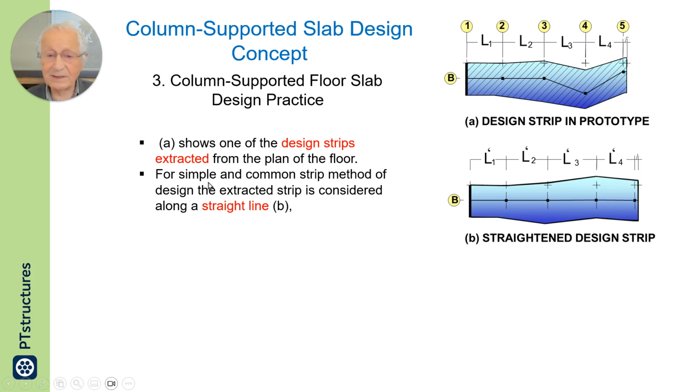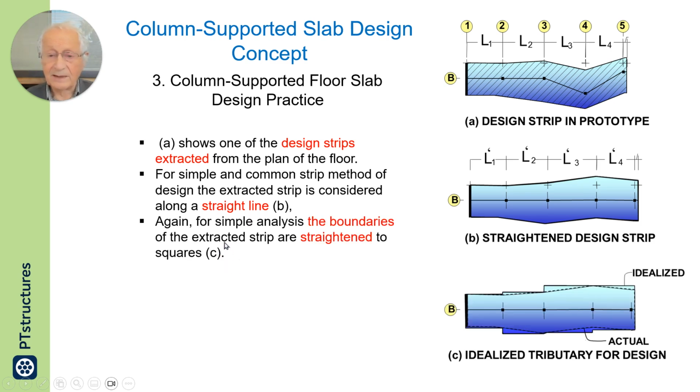For the simple and common strip method of design, the extracted strip is considered along a straight line, even though you have a little break along the line. And again, the boundaries of the extracted strip are straightened.